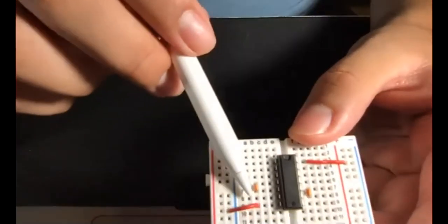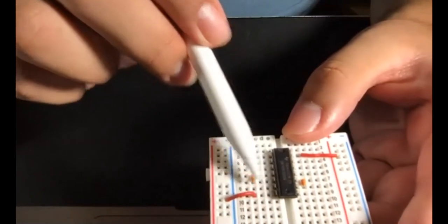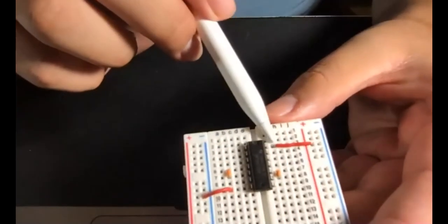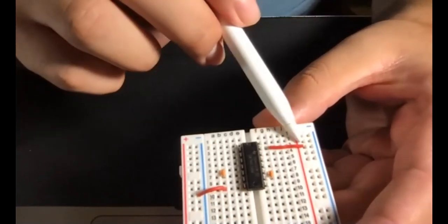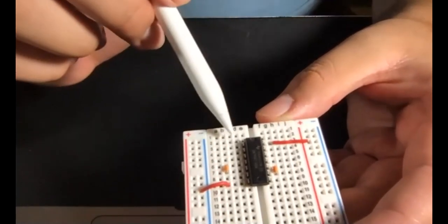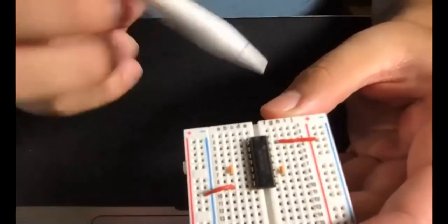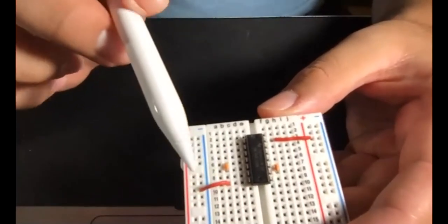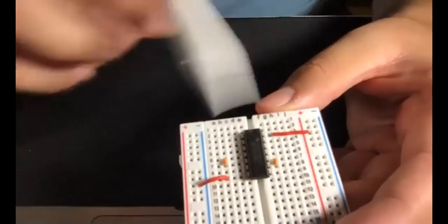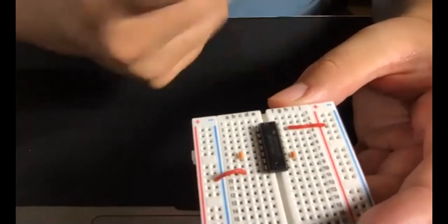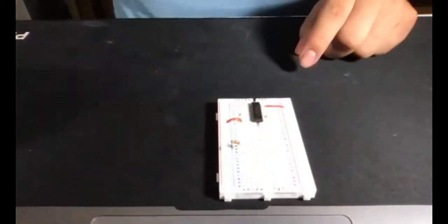This one here being the bottom left pin going to ground, which is stated in the data sheet. And then we have the top right pin going to power here. And that's basically how you would start. All this other extra stuff is just for demonstration later on, but you would typically want to make sure you're connecting your ground and your power. If either one of these is missing, your integrated circuit will not work. Your IC chip will not work. So now we're going to get onto some demoing.